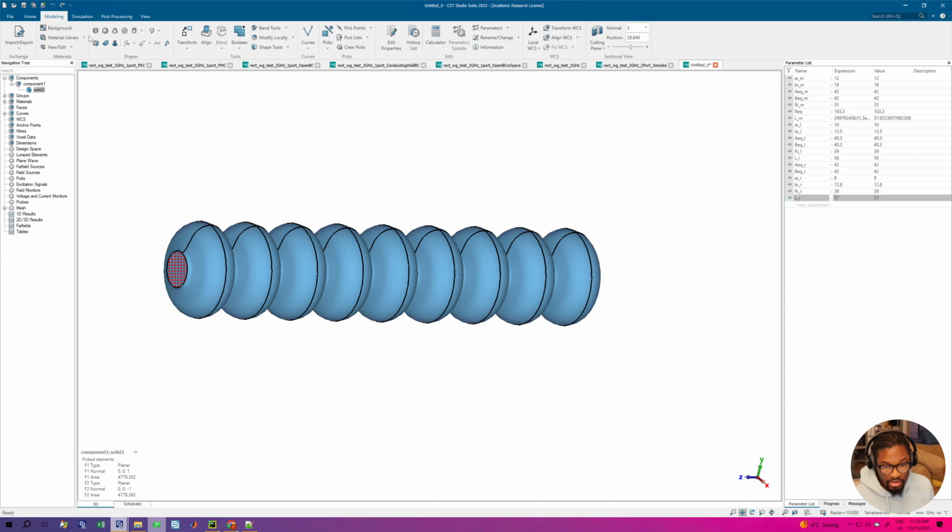So I have a frequency, it's in gigahertz. So let's see, 1 gigahertz to 2 gigahertz because I'm going to have 9 modes. No, 2 gigahertz is too much. I think 1.4 or 1.35 gigahertz. Okay, define my background. My background should be PEC, not normal. And then my boundaries should be PEC also.